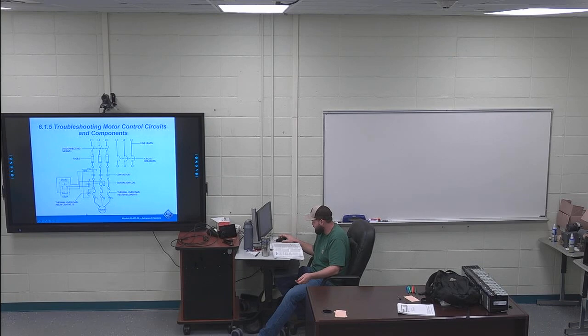Last line of that paragraph. Skipped a paragraph, and in the second to last paragraph on page 45, the last sentence is highlighted. The same basic procedure used to troubleshoot a motor starter works for contactors, because the motor starter is a contactor with added overload protection. A contactor is the same as in the lab, you've learned that by now. A motor starter is just a contactor with overloads built in underneath it.